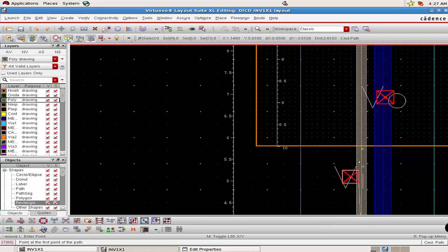As I stated before, the VIN and VO pins are basically made out of metal 2, but what is running at the bottom is metal 1 for the output pin and a poly which is running under the metal 2. Now how do we make a contact between the 2 different layers? It is through wire. Now let us first try to create a wire for this VIN input pin, which is made out of metal 2.